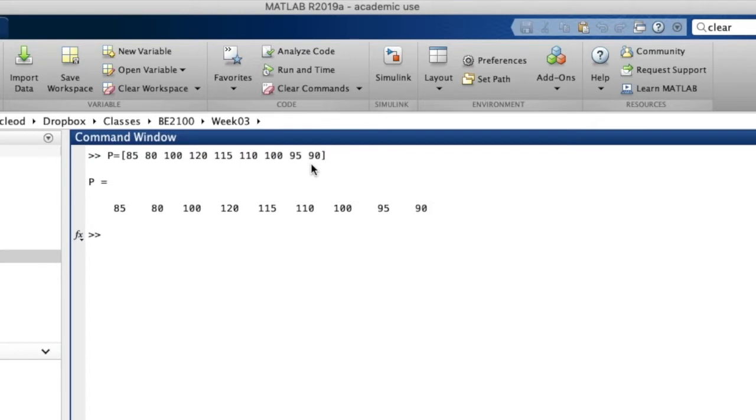Now I also want a time base, because that signal went from 0 to 0.8 seconds, so I want to create a time base, call it t, and in that time base I want to put all those same values that we read off the x-axis. They're pretty simple. In fact, because they're regularly spaced like this, there are ways we could automate the creation of this string, but let's do it this way. But at the end of this line, we're going to hit semicolon and see what happens.